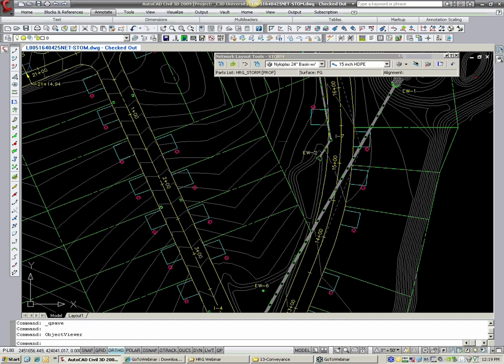It's AutoCAD, you'd think it would, right? But the design team got it right on this one. When you mirror a structure, it does not flip it upside down. I guess just in the definition of how an inlet is made, they recognize that the top needs to always be pointing up. So it does not flip it around. It works just fine. So mirroring a structure works fine. So hopefully that answers the question. But very good question. Put your hand down on that one.